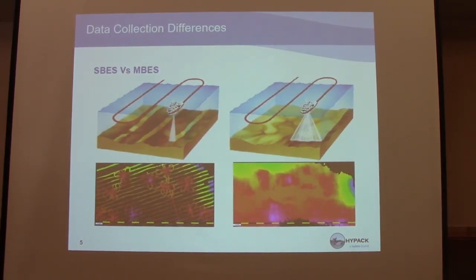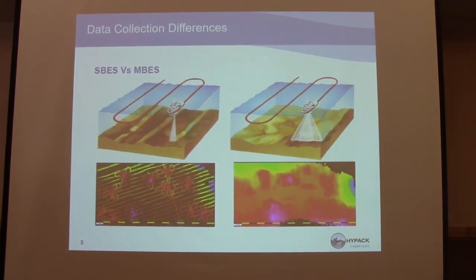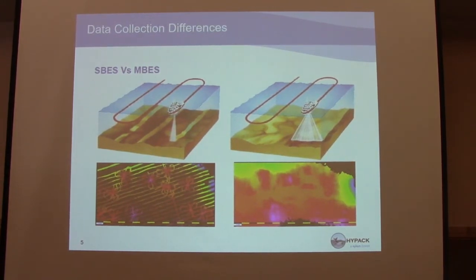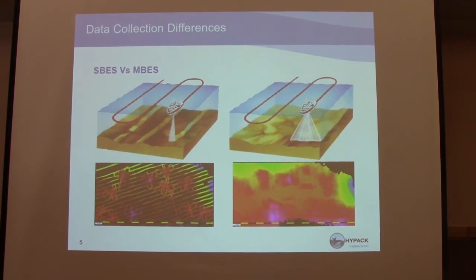Don't overlap the total capacity or the total swath width at 50% coverage. Paint the matrix where you're 65 degrees and in, port and starboard, and overlap those beams. That way when you get back into the office, you know that you have good overlap, 65 degrees and in. Does that make sense?